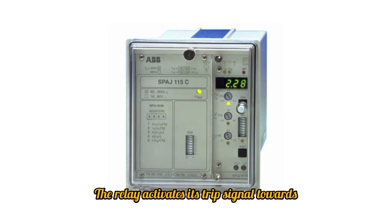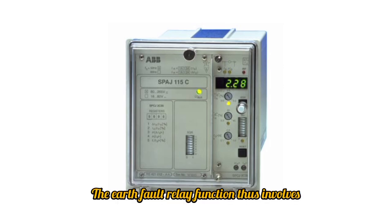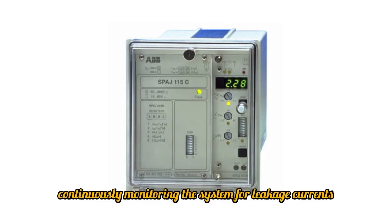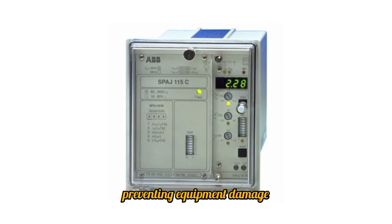The relay activates its trip signal towards the circuit breaker when the residual current reaches or surpasses the defined threshold. The earth fault relay function thus involves continuously monitoring the system for leakage currents and acting swiftly to isolate the faulty section, preventing equipment damage and potential hazards.